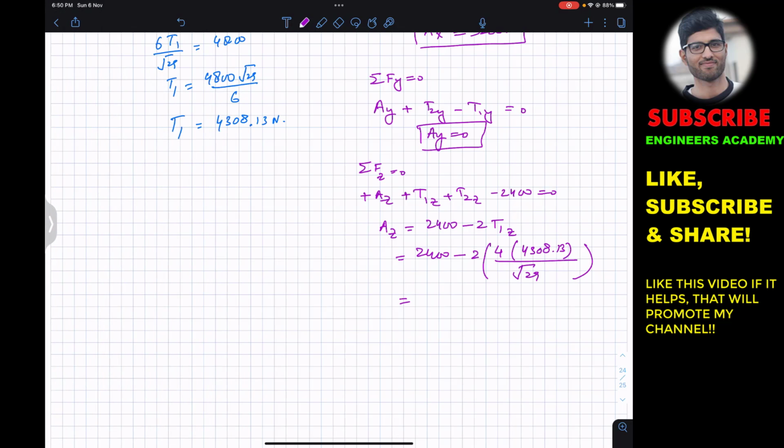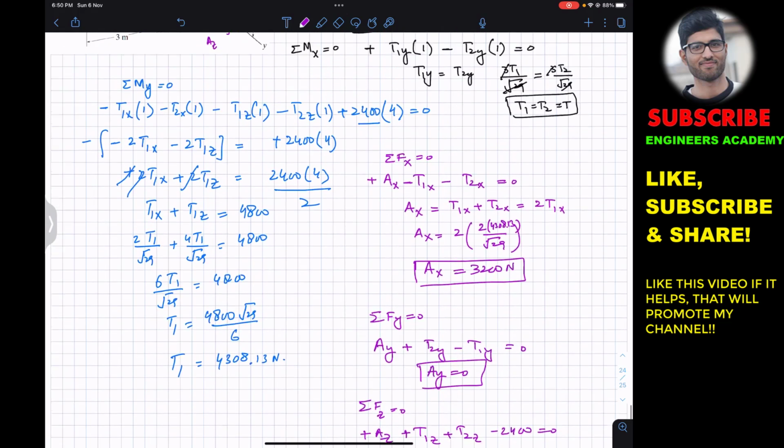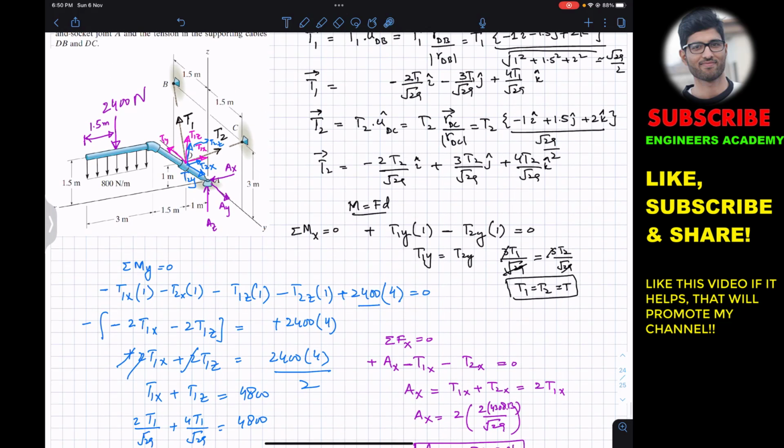So Az is approximately 4000, and we got a minus sign. The minus sign tells us that the actual direction of Az is downward; the assumed direction is not accurate. Az magnitude is 4000 newtons and it is acting in the downward direction.